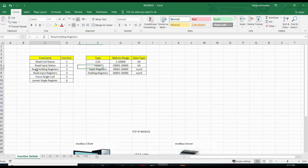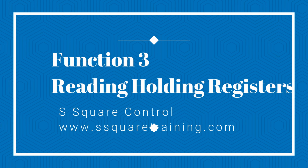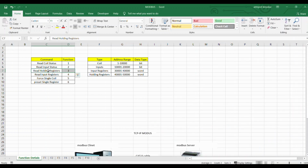Function 3 is reading holding registers. Holding registers have Modbus addresses 40,001 up to 50,000, and each holding register holds 16 bits, that is, each holding register is one word in length.